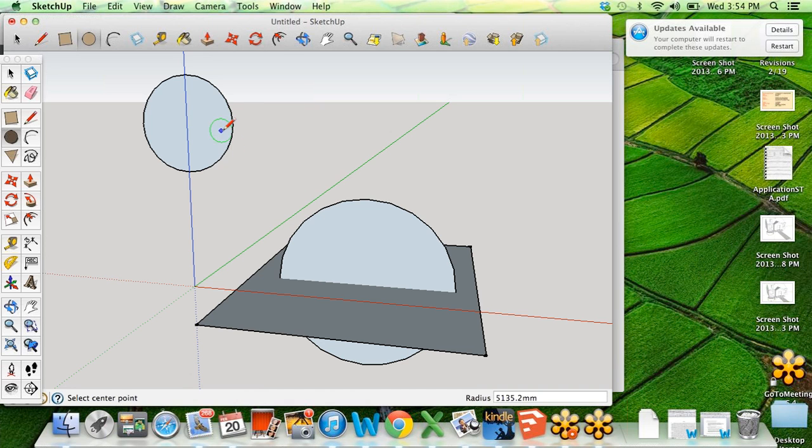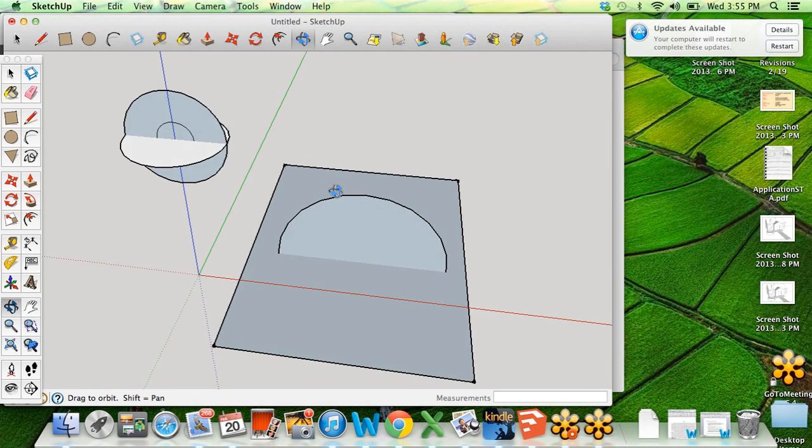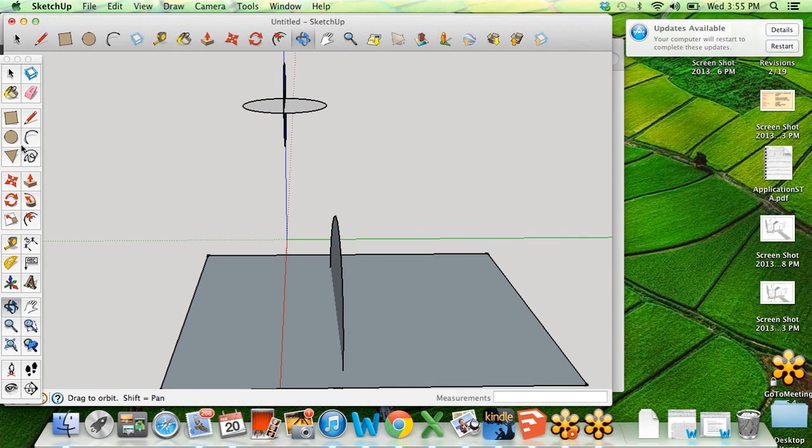And you can play around and see that if I wanted to draw another circle on this circle, it's only going to want me to draw it in the same orientation. But again, I can choose this flat orientation with my Shift key, not let go of my Shift key, and then I can add another circle there. All right, so do you guys see what I'm doing here?